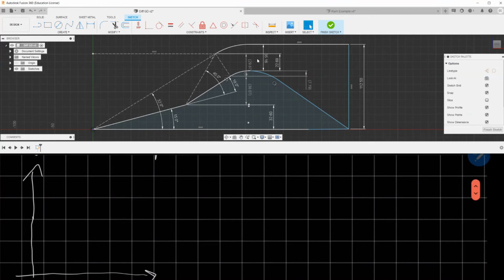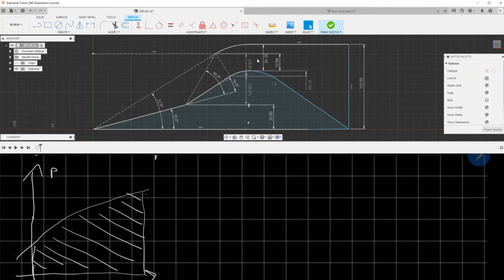So, for example, I just need to find the variation of average pressure, right, from the area. Take the vertical axis, the pressure, and calculate the average pressure on the wall. Okay, and so this is P. And this integral over the area will be this area, right? You know that the integral is the area once you plot it in this way.